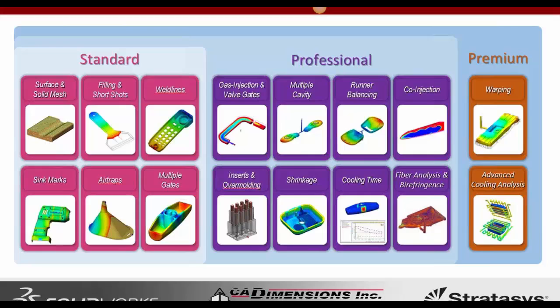And last but not least, we also considered the cooling process within the analysis to ensure that we're getting the most precise results when it comes to warping. So it's not just a constant mold temperature. The mold temperature is different at different areas due to the cooling process.